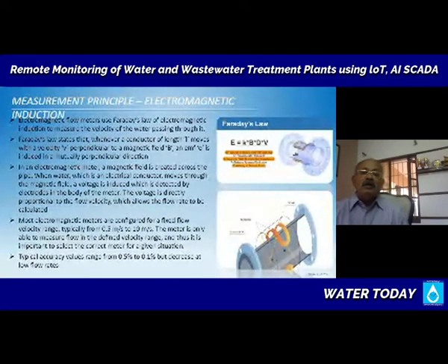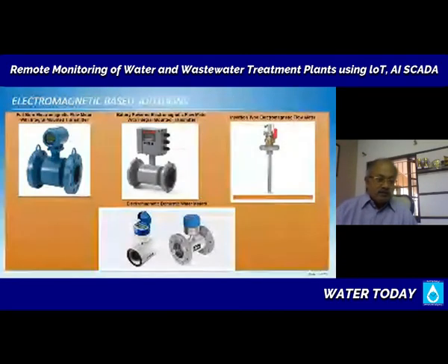So please be careful in selecting where you put the sensor, because we see many cases where people go and specify, oh, water measurement, magnetic flow meter. And then later you find that the meters are not functional. So please, if you get the opportunity, select the meters to work for the process that you have, and don't try to adapt the process to your measurement scenario.